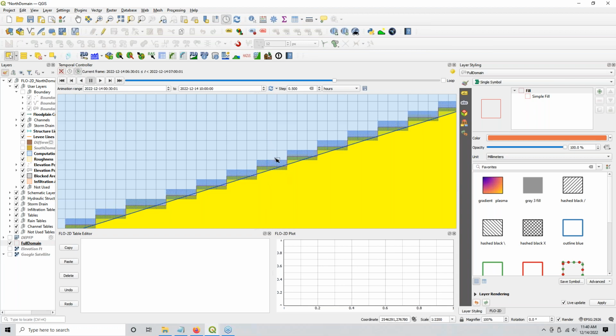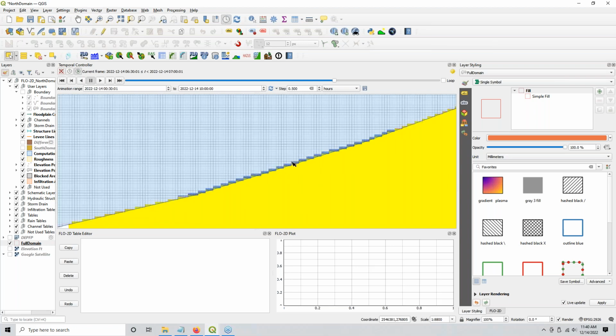In this case, that's predominantly south. Regardless of whether or not we're getting the exact diagonal flow, we are definitely getting the total volume. And of course, remember that as soon as this water crosses this domain divide, you're losing things like your velocities and your momentums. They have to be reestablished on the secondary domain. So keep that in mind when you build domains.